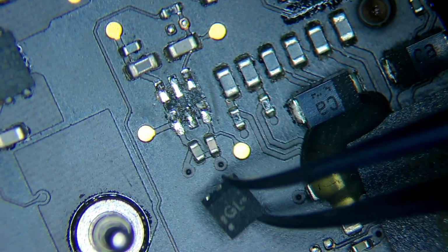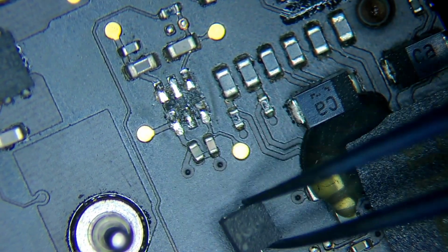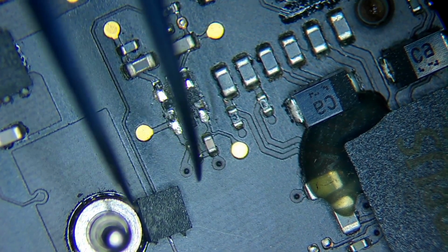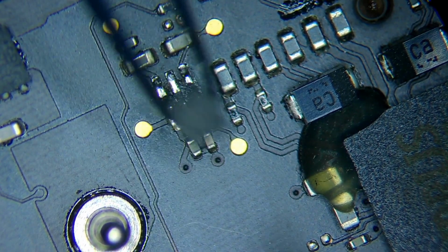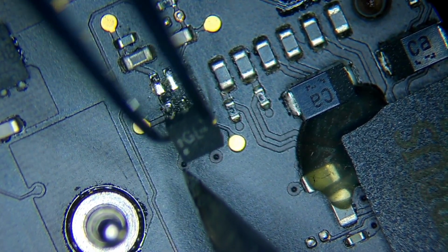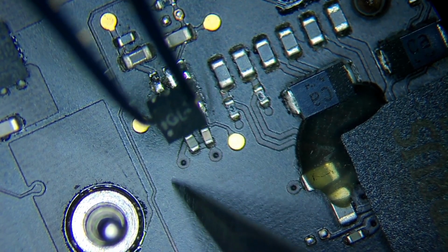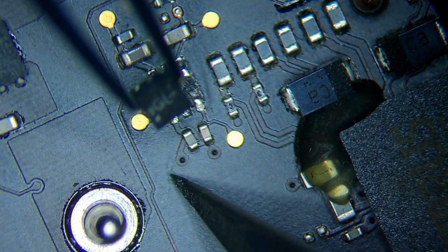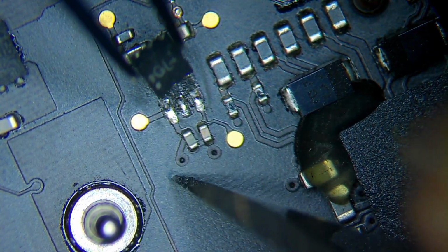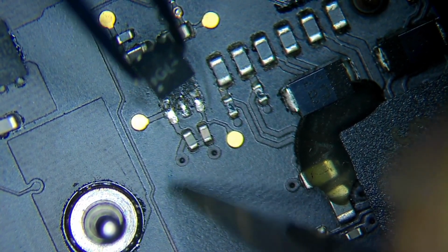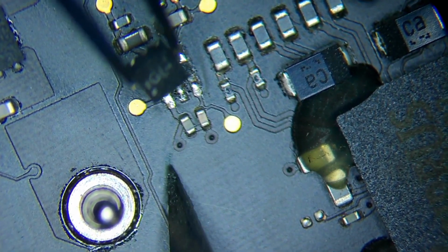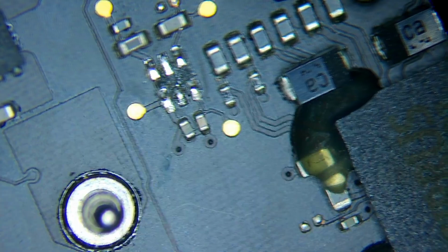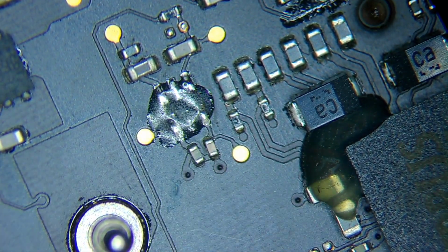Okay, so we removed the chip, and so we don't forget the orientation of the chip. It has a dot here, so I'm gonna just scrape right like that, really carefully, on the surface of the board without damaging it. Okay, and I'm gonna clean the pads and see if we still have a short,